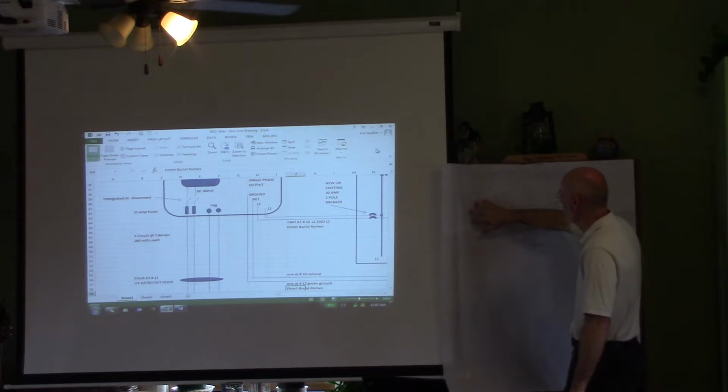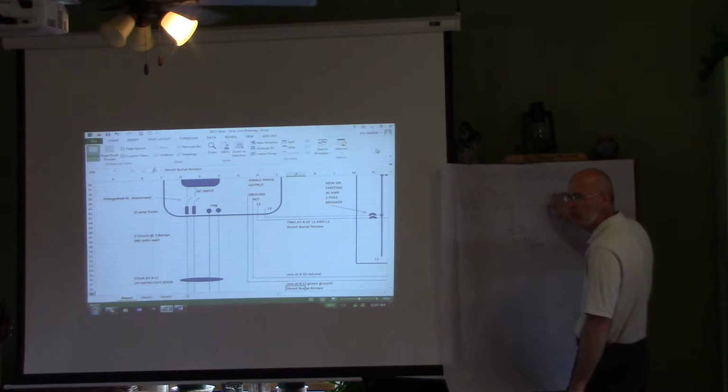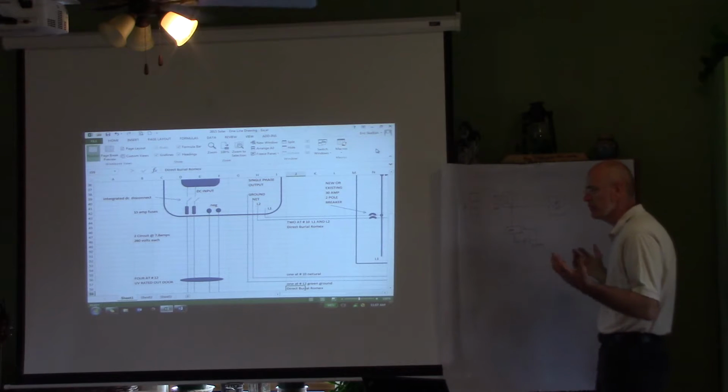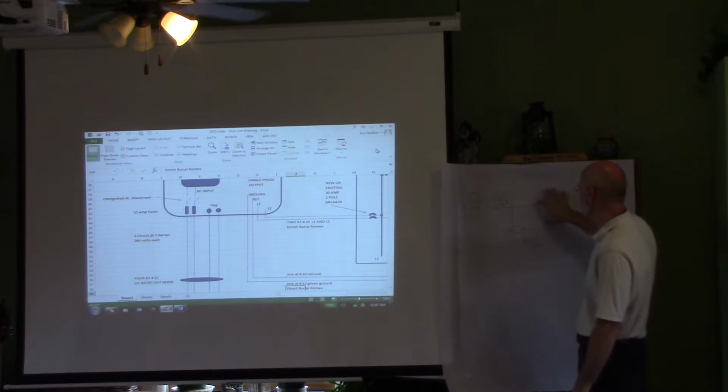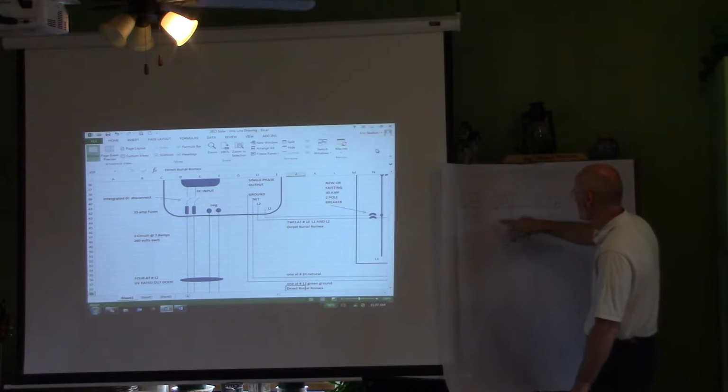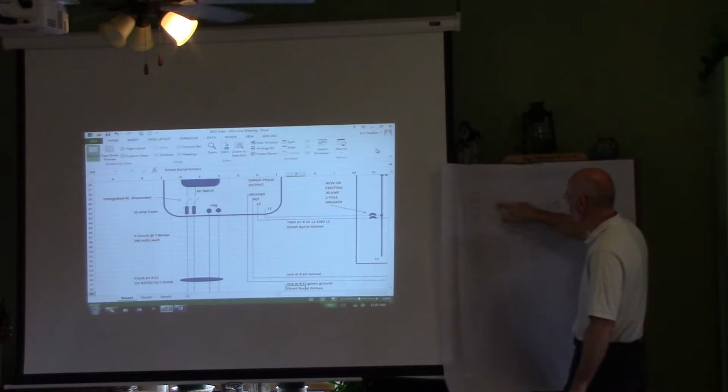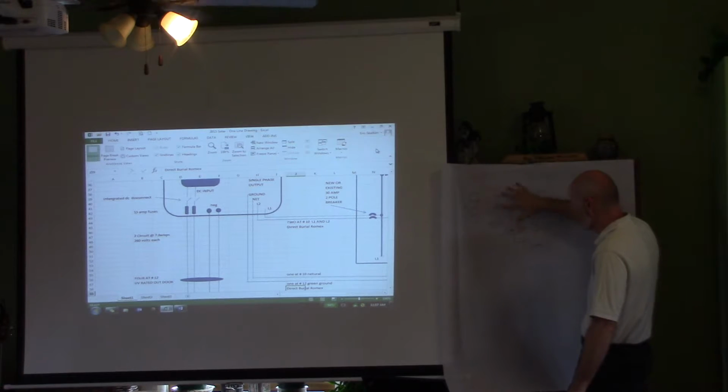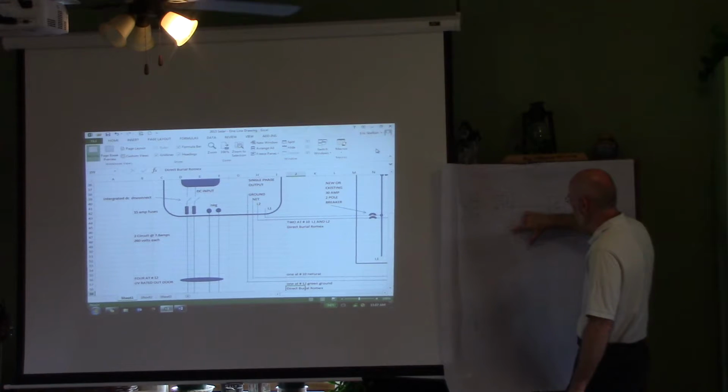In the daytime, the DC gets converted to AC just like before, and there may or may not be load in the daytime. Most off-grid people are using the sunlight, so they don't turn their lights on during the day. So they know that they need to charge their batteries during the day. So the power goes in, goes from DC to AC, and this inverter can take the DC. If it's not going over to a load, the DC, or whatever portion, it's a blend, the portion of DC can come down here to the charge controller and charge the batteries.